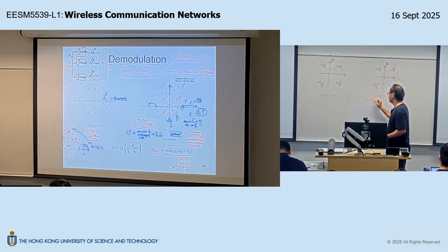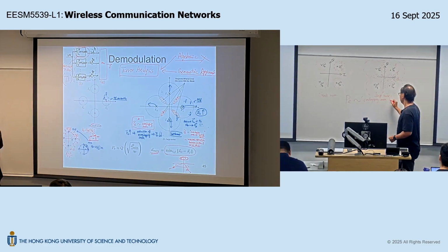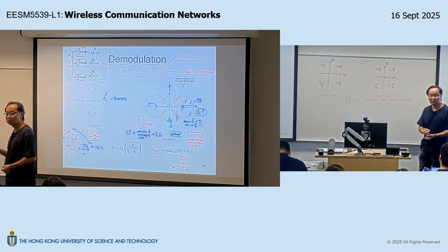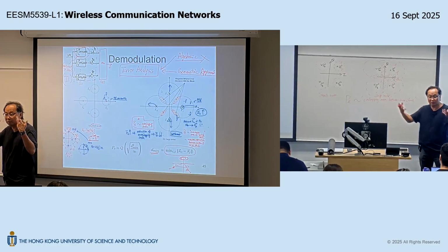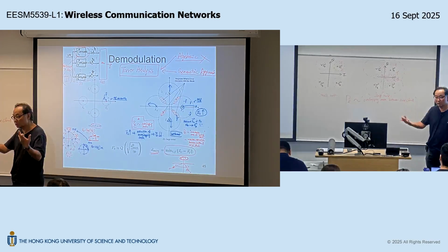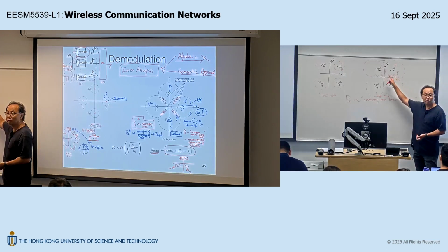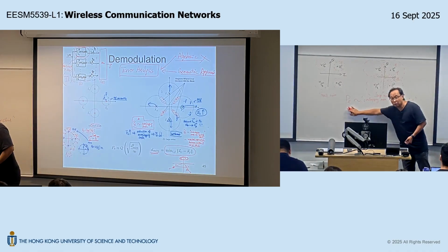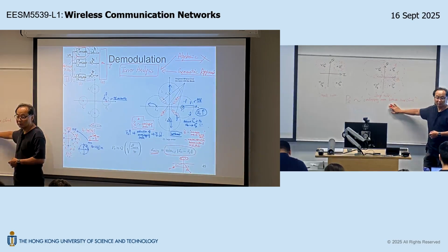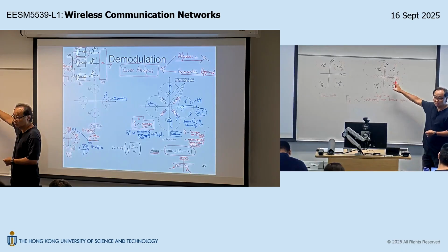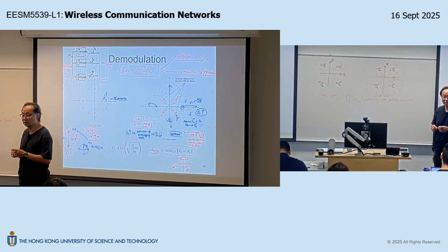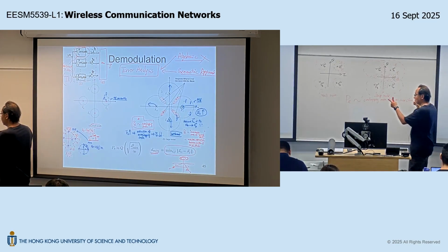overlapping area between noise clouds. Can you see that? We all agree with this statement, right? Because we visualize when the mistakes will happen: when the observation lies within this overlapping area in the signal space. Okay? So how likely you make a mistake, the so-called error probability, of course, depends on how big your overlapping area is. The bigger the overlapping area, the higher the probability that you will land on this overlapping area. Is that okay? Now, this is a very important intuition.